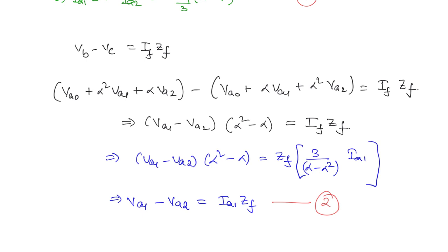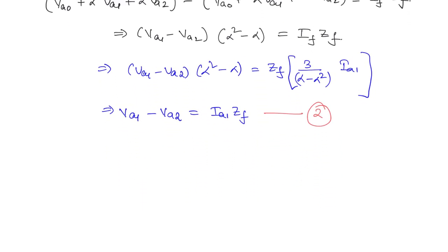So we will now see what this interconnection is. Now, you have to understand that the zero sequence current we got as 0, that means no zero sequence current will flow. So we do not have to include the zero sequence network, we are only concerned with the positive and the negative sequence. So this is the positive sequence network.